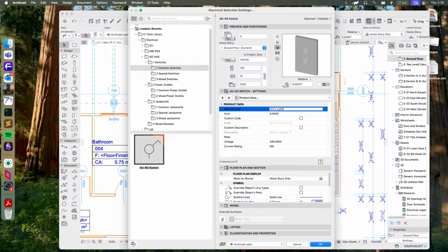The next hotspot on the edge is to create a split in this edge. So to turn it into two edges for whatever reason. Obviously, there's plenty of reasons why you might want to split it so that you can do a junction or something like that. This will allow us to do that. Very similar to how any standard polygon editing in ArchiCAD does. If you click on the node on an edge, it will split the edge into two. That's what this one does.